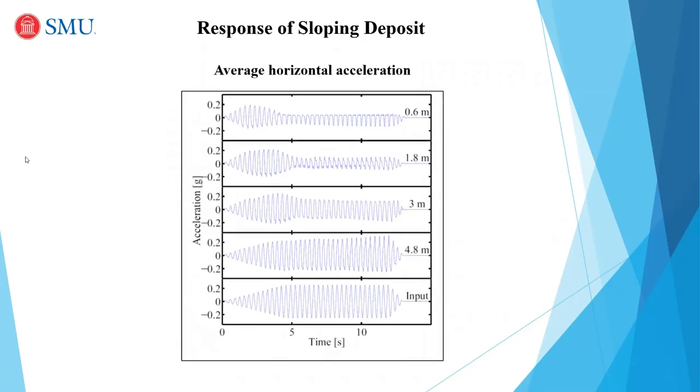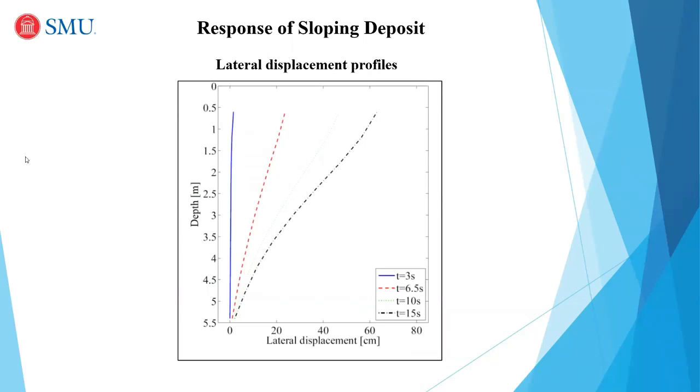and reduction in pore pressure. Acceleration doesn't completely die, as we have seen in the case of level ground. Again, you see here these negative spikes. These are very common. Anyone with knowledge of the response of these systems who has seen centrifuge tests will agree that this is something we typically see in sloping ground simulations, where we have these negative spikes, which happen again when the soil is moving upslope because of dilation. But liquefaction of this sloping ground caused a lot of lateral deformation, up to about 60 centimeters by the end of shaking. That's significant, as you may imagine.